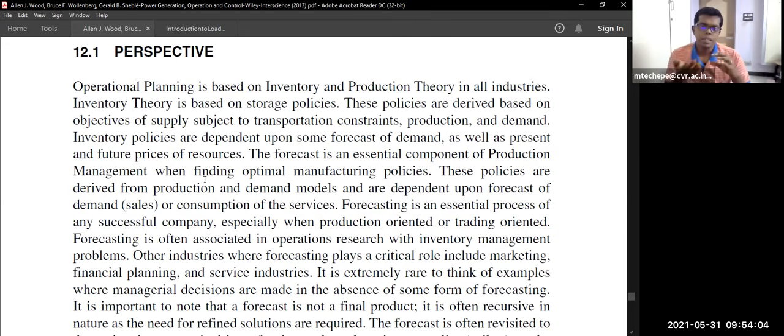The changes we account for by generating more. Say for example 13,000 megawatt is today's load. We make it some 13,500 megawatt. We are generating 500 megawatt more only. Why? Because suddenly the load may increase. Suddenly the load may also decrease, to 12,500 megawatt.